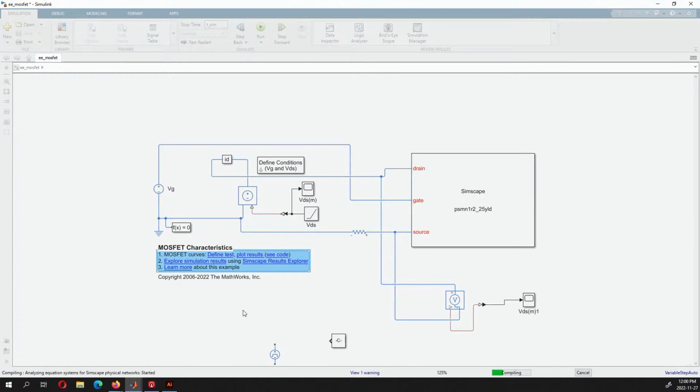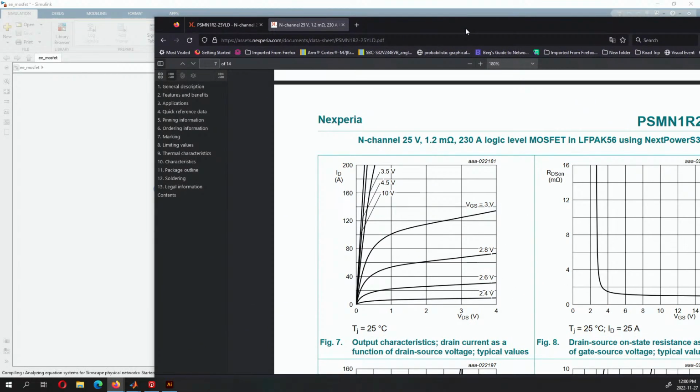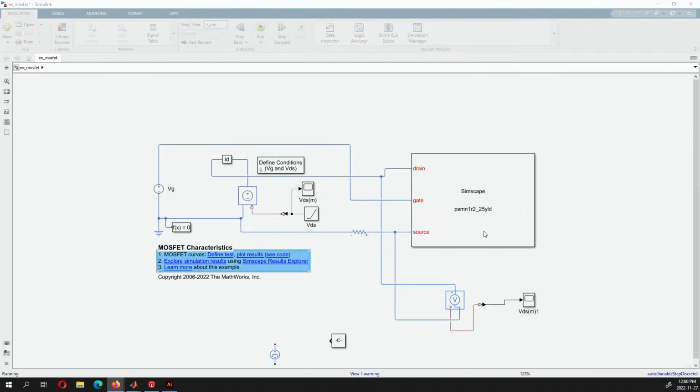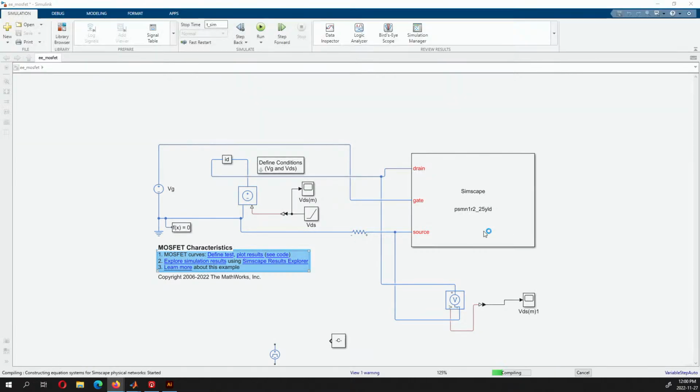And you can minimize that loss by increasing the gate voltage. That's why this graph is so important, because this directly relates to the MOSFET you're selecting and whether this MOSFET is appropriate for your use case. And if it is, you want to know what voltage you want to hit your gate so that you're minimizing the resistance. So that's why this is such an important basic characteristic that you want to analyze before you select a MOSFET.